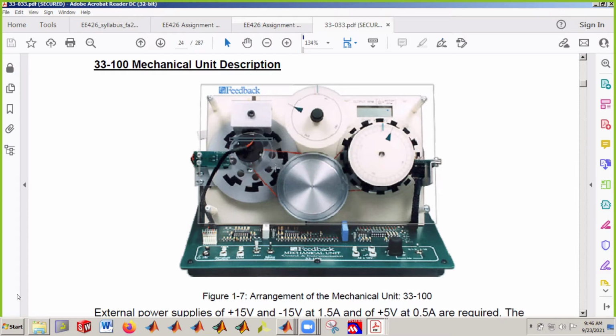That is why we study step responses, because sometimes you just want to change the system from one state to another. A step response is one way for you to figure out how fast or what kind of performance you will get if you put in a step command. That is the reason why we study steps. You want to move your system from a specific position to another, and see how fast you can do this and what kind of performance you get. You usually want to apply a step response so that you can figure this out.